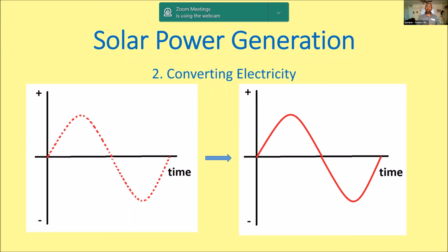The AC signal leaves your power conversion station and is raised up to a higher voltage. Voltage is equivalent to if you're standing on top of a cliff and you're to jump down. The higher the cliff is, the more potential you have, or voltage. The reason we do that is because when you raise your voltage higher, that power can go for a longer distance. That power is then sent over to the electrical grid, where it's taken over to